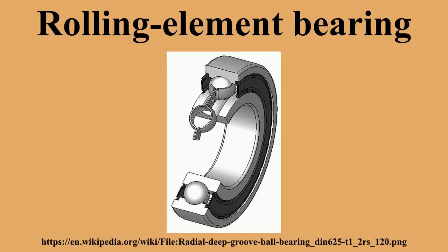The needed bearing lifetime also varies with the application. For example, Harris reports in his rolling bearing analysis on an oxygen pump bearing in the U.S. Space Shuttle which could not be adequately isolated from the liquid oxygen being pumped. All lubricants reacted with the oxygen, leading to fires and other failures. The solution was to lubricate the bearing with the oxygen.